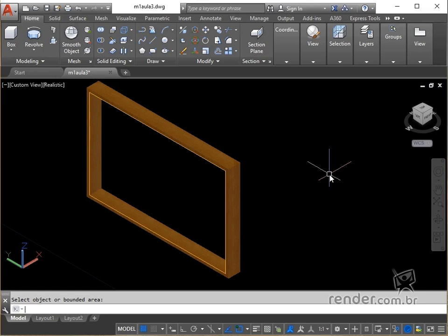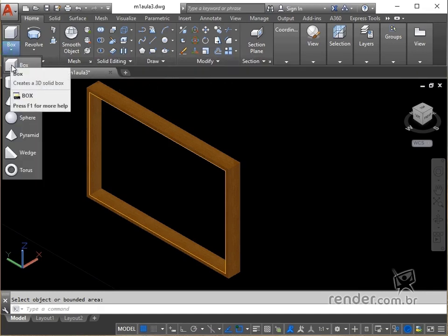The next step will be to create the frames of one of the sashes, which are the structures that support the glazing in windows, doors, window walls, among others. For this, we will do a procedure similar to that used to create the sill, keep track.